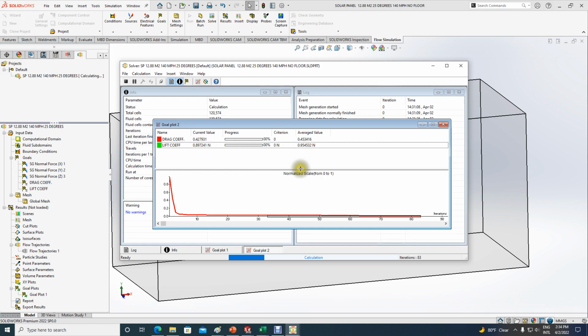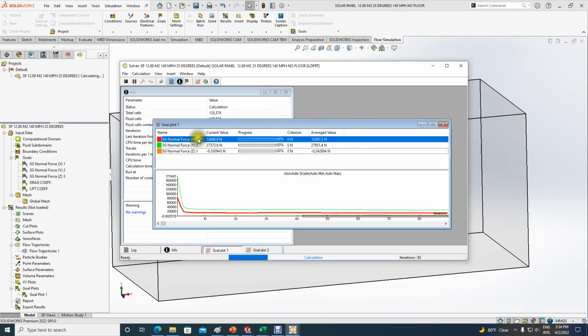We'll see now how the forces are. The forces should get close to what we got the first time. Here we go. It was about 26, you remember? 26,000, and it was about 12,000 on this one. This was with a very low resolution, I think it was for the mesh setting. It's starting to get pretty close now. It's closing. Probably it will maybe repeat itself basically with the same number, even with a higher resolution.